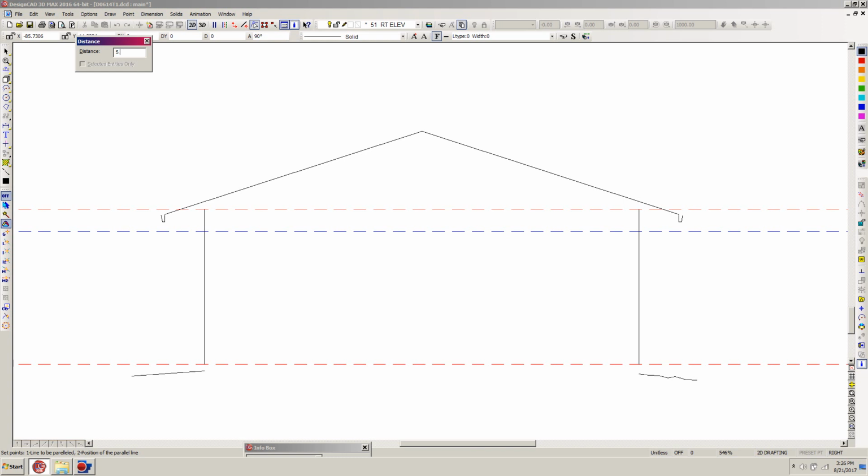It'll be 6.125 inches, because it'll be the total of the roof sheathing that sits on top of the 2x6 barge rafter. So 5/8 inch roof sheathing plus 5.5 inches for the barge rafter equals 6 1/8 inches. So I'm going to type in 6.125 inches, which is 6 1/8 inches.